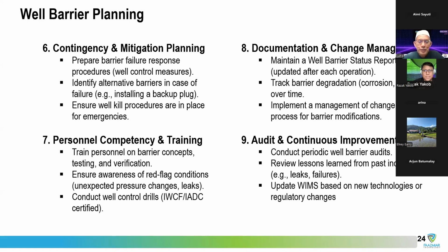So it's a different understanding about the situation of the well, and then, of course, how to manage well control in this different environment. For example, if you're drilling a well, talking about open hole, you drill, you have your cemented casing, you drill open hole, you have a kick, then you have to manage the weaknesses of the open hole, plus the weaknesses of your casing, if any, and then even your surface equipment.